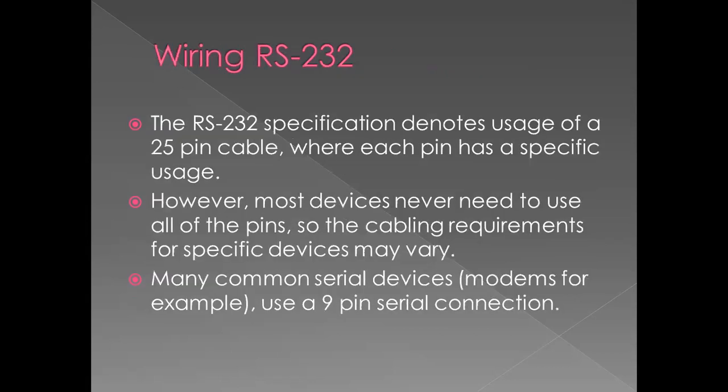Wiring of the RS-232. The RS-232 specification denotes the usage of a 25-pin cable, where each pin has a specific usage, though most devices never need to use all of the pins. So the cabling requirements for specific devices may vary. Many common serial devices, modems for example, use a 9-pin serial connection.